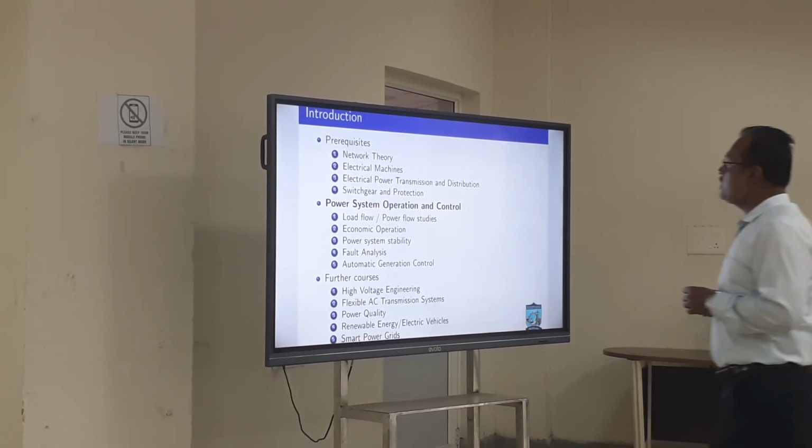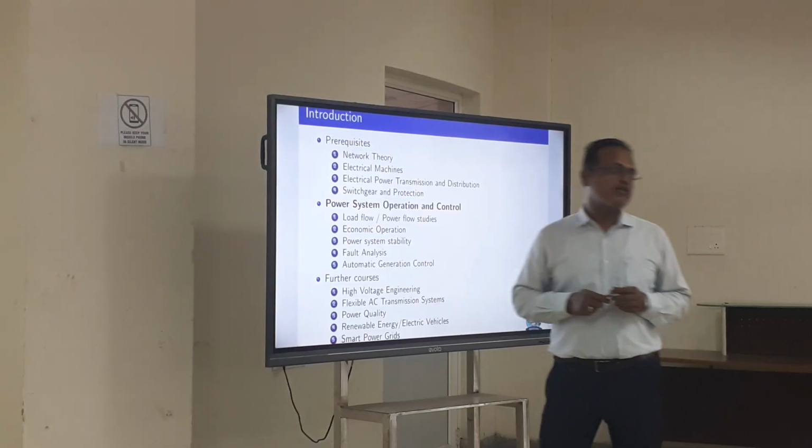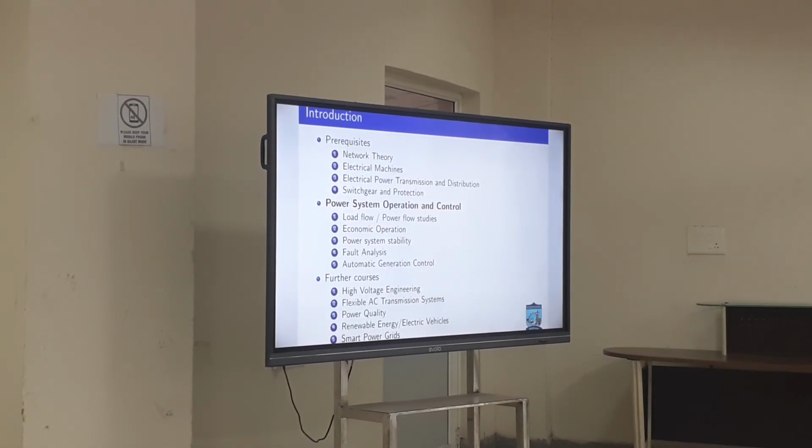Okay. The second module is economic operation of power systems. Now we have a certain demand in the power system, and we have to meet the demand. So how can it be done at least cost. Okay. But this is mostly related to thermal generation, right? The economic dispatch as it was developed was for thermal generation, because thermal generators involve coal, and we have to minimize the consumption of the coal. Later emission was introduced: minimize coal consumption as well as minimize emissions.